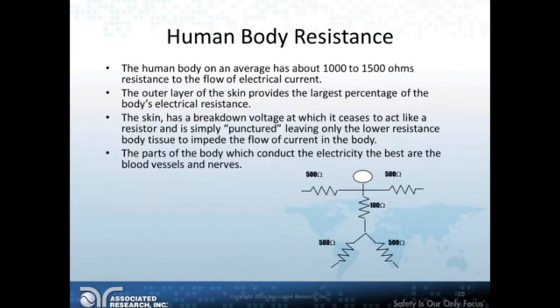It also assumes a much lowered resistance. Maybe my hands are wet. If you wanted to run an experiment on your own, if you have a simple LCR meter, go ahead and put it in just DC resistance and grab one side with one hand and one side with the other, and you'll see usually it's much higher than that.